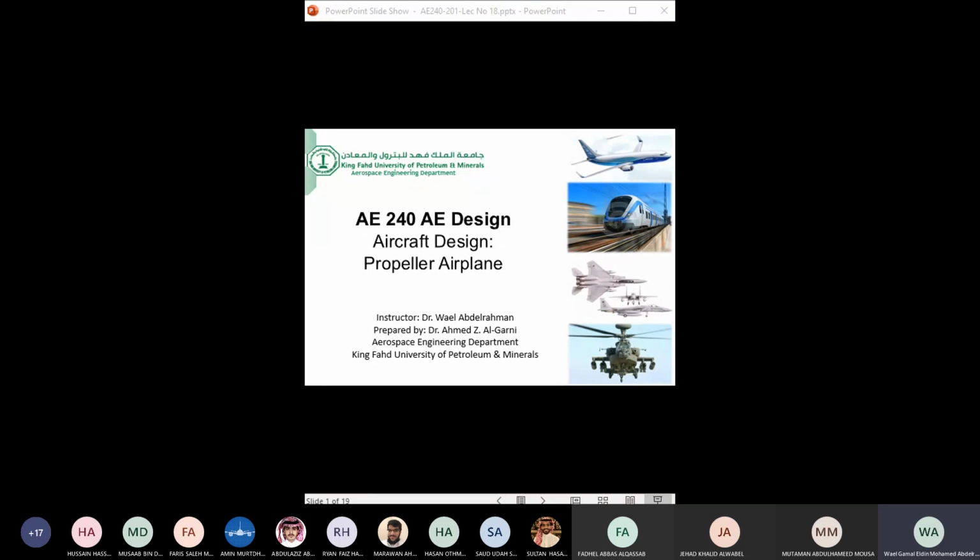So mention the airfoil. What's the airfoil, and what's the L over D of that airfoil that's being used? Okay, thank you. Now, if I don't have any information, I would visit a library of airfoils, and I would see, for example, the 4-digit series. What type of airfoil does the aircraft use? Do you remember the number? No, I don't remember. Typically, if you want a high lift airfoil, it would be a 4-digit series. So I will go and look at the 4-digit series, and I would try to figure out a good one. But in this case, yes, I agree, 19 is not too high. Feel free to use it.